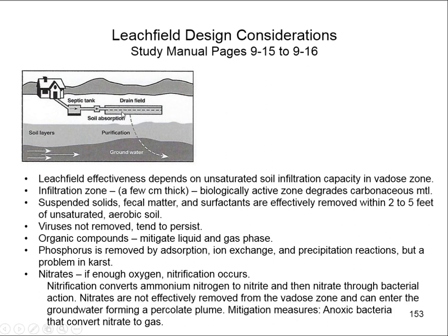And that's why if you have 5 feet between the leach field and the groundwater, usually that was considered enough freeboard to filter out our human waste. Well, we have floods. We, as I mentioned, are putting in other things into these drain fields.